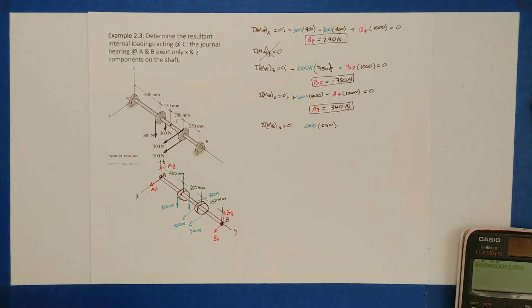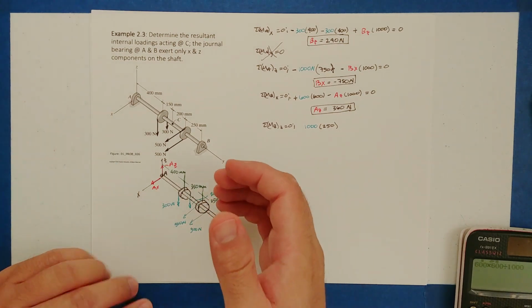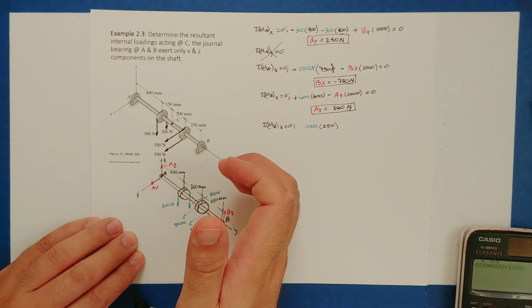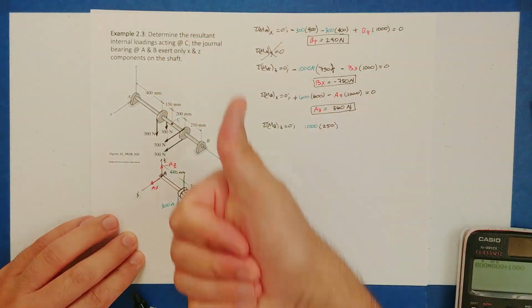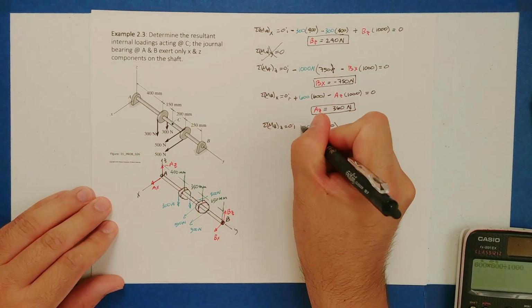And then what is the direction along the Z? Well, if I'm pinned here and I push that way, look at the right hand, almost pointing to the right answer, right? It's going to push the whole shaft that direction. My thumb is pointing in the positive z direction, so that's a positive moment.